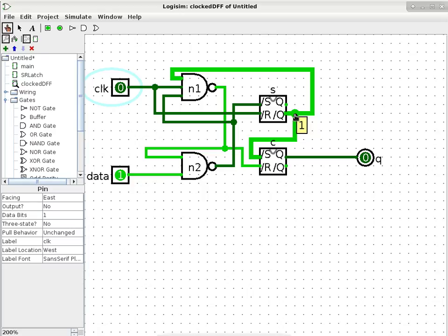When this goes from 1 to 0, the first place it goes to is the C SR latch. So the C SR latch is going to see /S going from 1 to a 0, which means, hey, set Q pin. So the Q pin is going to go from a 0 to a 1. But where else is it going? It's also going back to the N1 NAND gate. So now the N1 will still be outputting the same thing because clock is a 1. Clock is a 1, and so it will still maintain the output to be a 0. And that's the extent of the analysis.